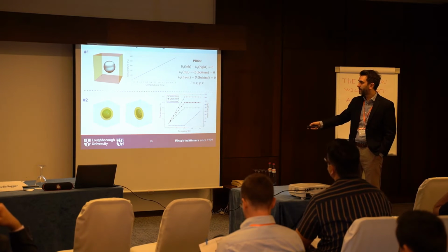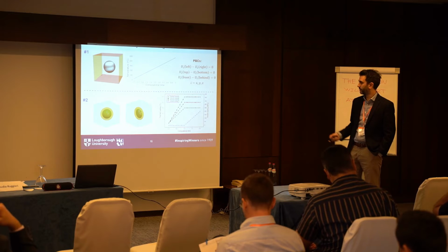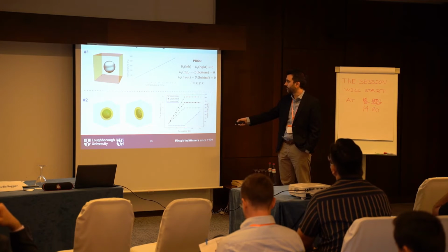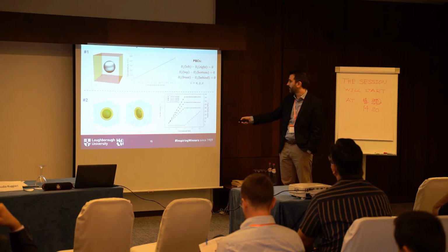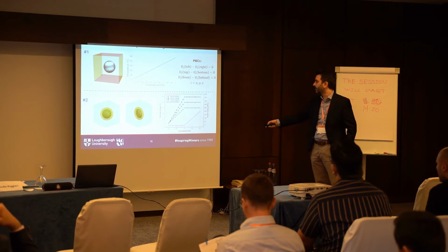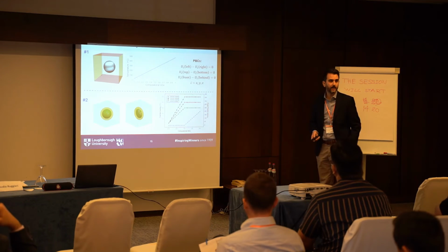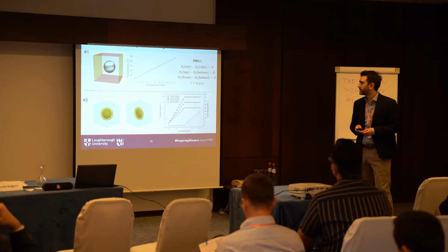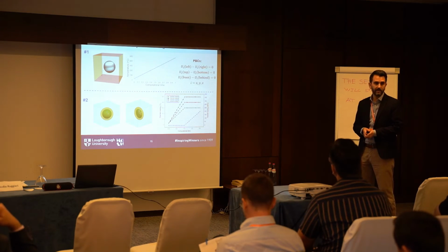The same happens here, but the model has different loading conditions. So what we have here is first an increase of temperature, right? So from 0 we go to 300, 400, or 500. We heat up essentially the material, and then we load it up to 200 megapascal in tension. Why is that? Because we have relevant experimental studies that we can use to validate our model.